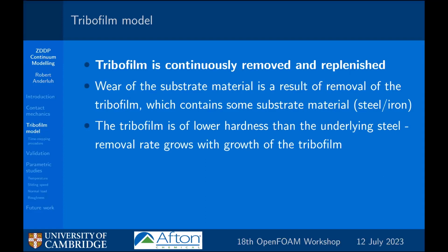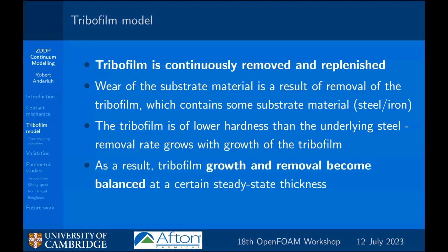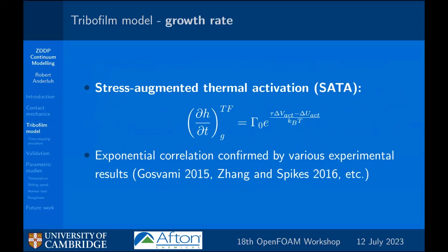And important to understand is that the tribofilm, as it grows, its hardness is decreasing, which means wear is going to increase as it grows. And because of this fact, we have a steady state behavior at a certain thickness because the growth and removal balance at some point. So about growth, this is quite an established approach to doing this, and there's a lot of different work going into determining how this works. So growth